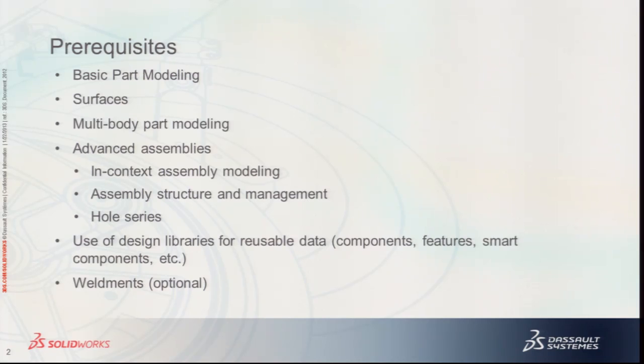Of course, basic part modeling, and then knowing about surfaces and multi-body part modeling. And if you go downstream and you're actually building a mold base, knowing a little bit about assemblies and how they work, and then some of the various components. I even get into a little bit of weldment functionality. That's how I've done ejector pins, and so that's why I have that on the list. So just a basic familiarity with some of the tools here.